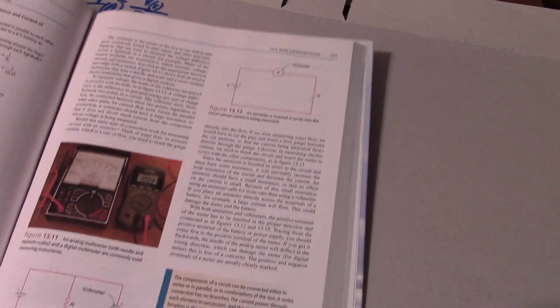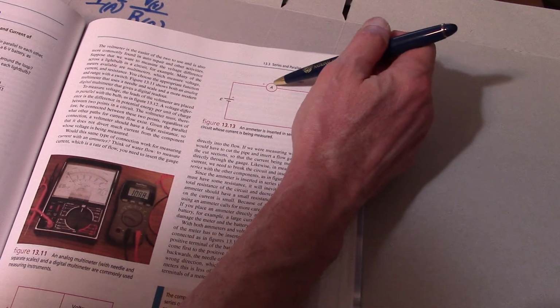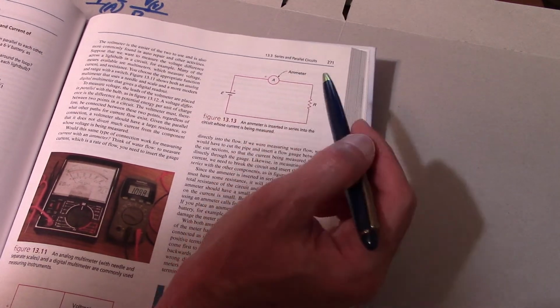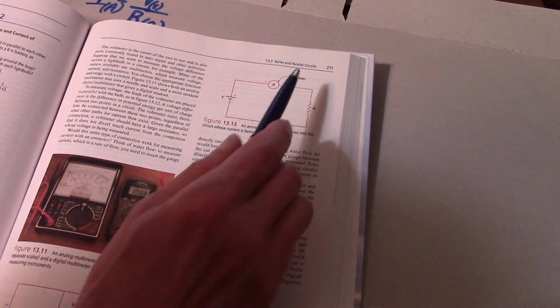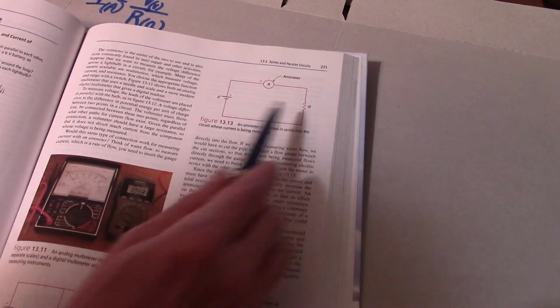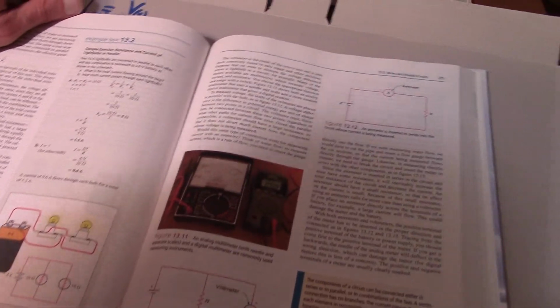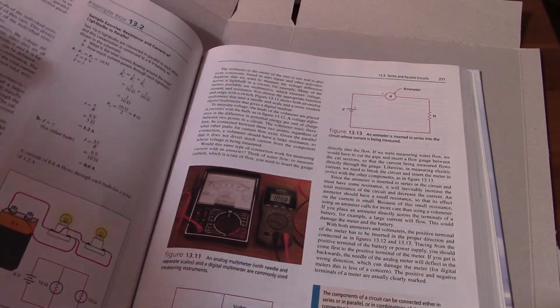The other one that the book isn't showing, I'm telling you about it. There's a type of meter where all you can do is it just wraps around the wire, and then the field that is produced by the electrons going through, you can measure the current that way. That's the more typical when you're troubleshooting, or when your mechanic is trying to fix an electrical problem in your car. That's what he would use. Whenever electricity flows, there's a magnetic field. There's electric fields, magnetic fields. They all go hand in hand.